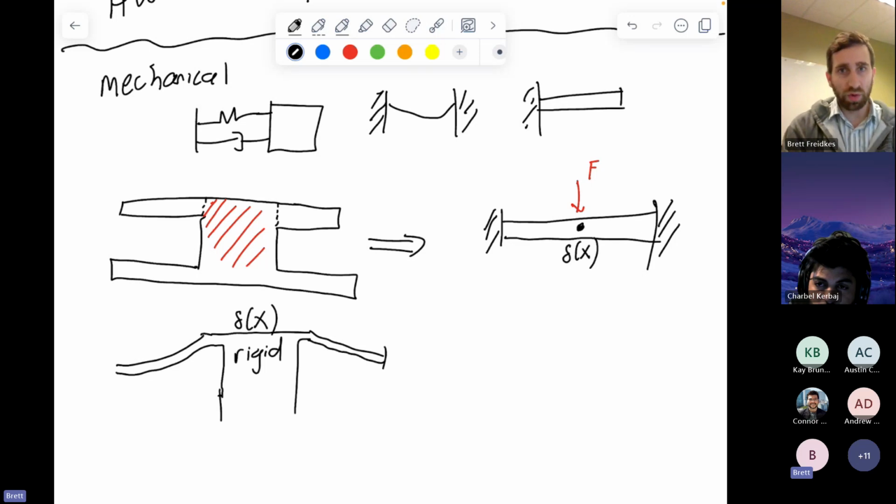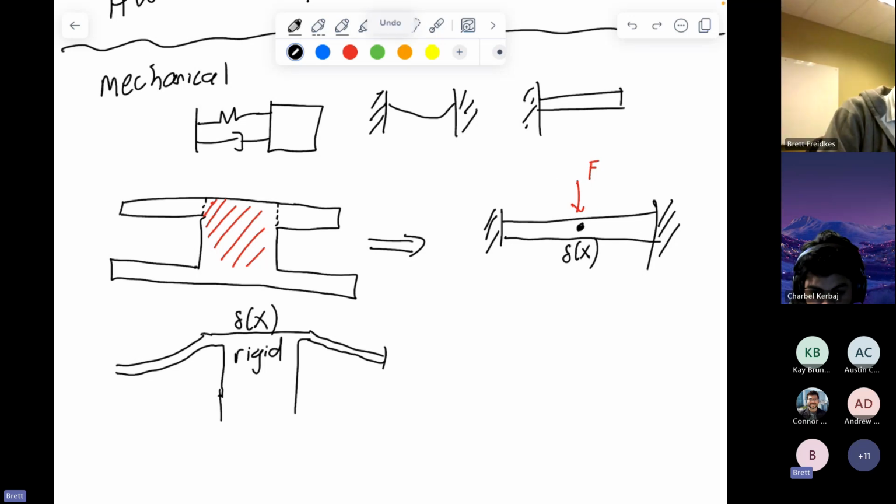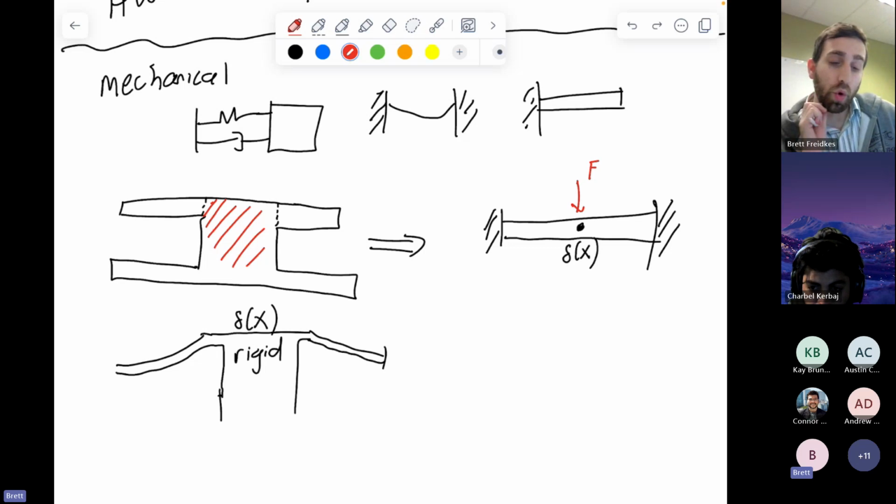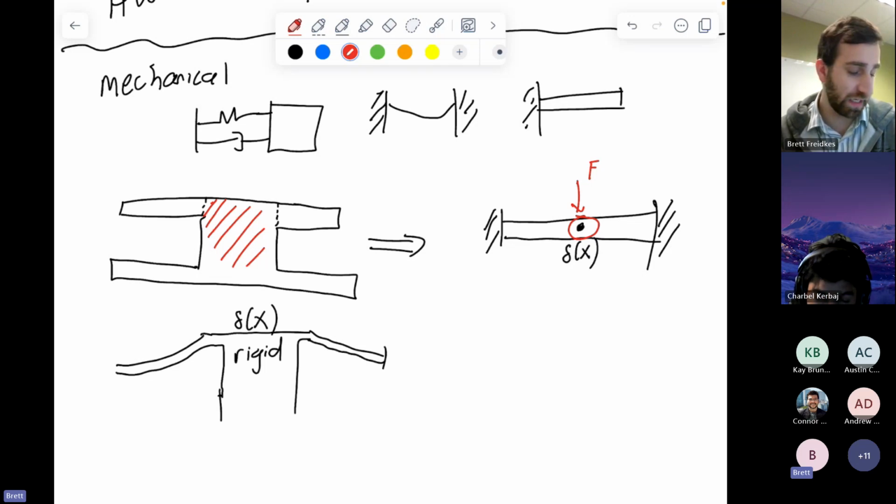So we don't need to model what's happening in between in the square region because it all has the same deflection. The way that we account for that is by including this force that is possibly acting over the square from some external thing like an acceleration or some other type of thing. We do need to know how the block deflects, but that will be what the deflection here is. So we would solve this clamped beam using Euler-Bernoulli or Castigliano's theorem, something we've talked about previously.